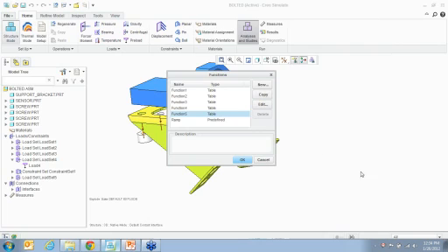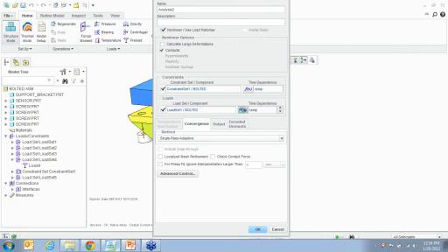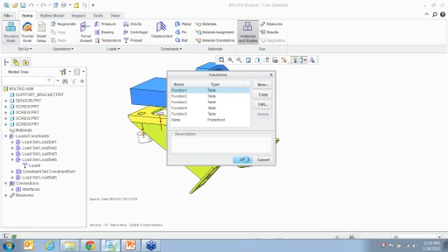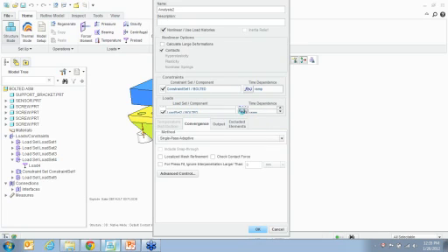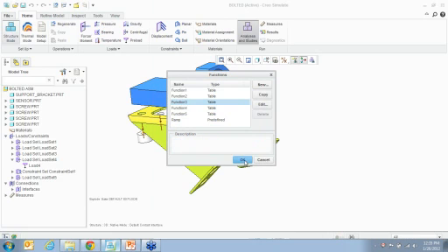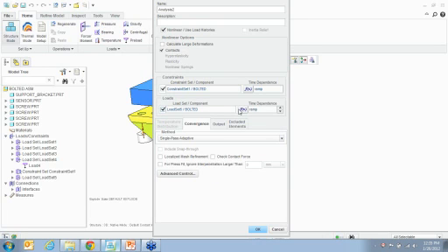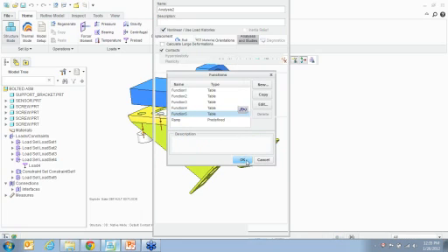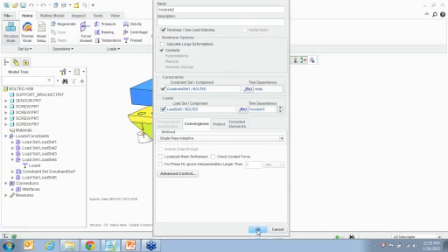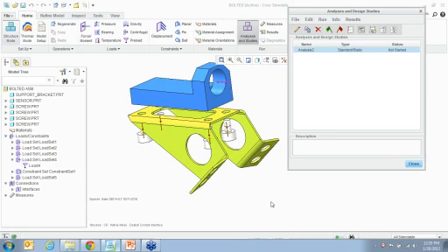right here. So what I'm trying to say is, if I say the first bolt uses table 1, second bolt uses table 2, third bolt uses table 3, fourth bolt uses table 4, and the fifth bolt uses table 5. So what this does is that for the first 1 second, only the first bolt load is applied. After that's applied with its preload, it's fixed in place, then the second one's applied, then the third one, then the fourth, and then finally the main load.